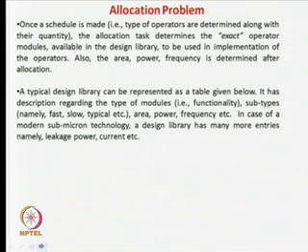But now we are not telling the exact nature of the multiplier or the exact nature of the adder. Lot of adders are possible and they may be available in the library, like ripple carry adder, carry look ahead adder, carry save adder. Some adders are faster, some are slower. Faster adders are generally high in area and take more power, we all know that. Slower adders are generally less area and take less power, and so forth.